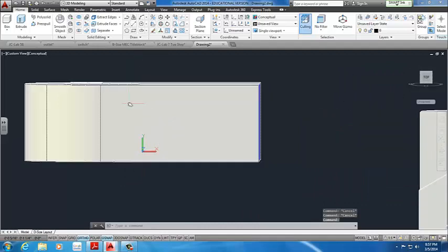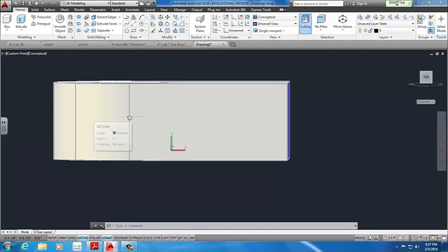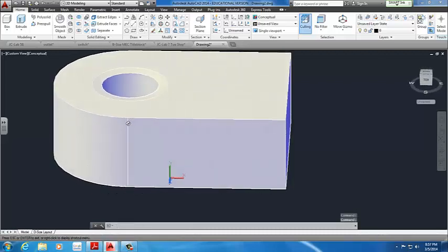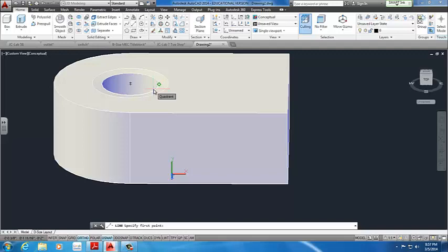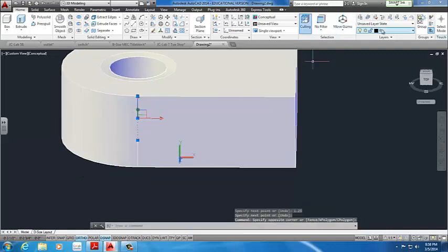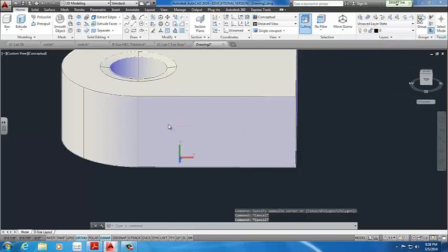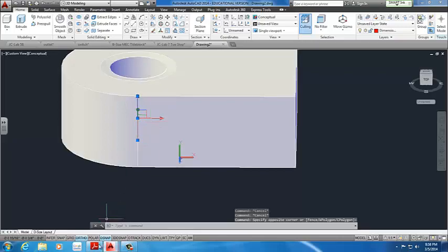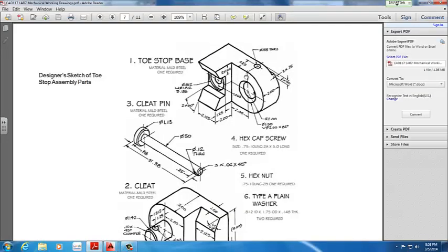And we're going to use the line command to figure out exactly where to place the circle, which will be exactly at where this arc ends, so this line right here. Except it's going to be a distance of 1.125 from the wall. So I'm going to change the color here so you guys can see it better. I guess it's not working, but that's where it ends. It actually is lower than the center, so keep that in mind. So if you see from here, it is actually centered at this arc, 1.25 down, and it's 0.55 diameter through.